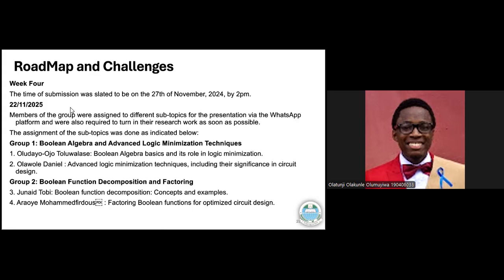If I want to compare it to K-map and Quine-McCluskey, I'll say in a way it is closer to the way we are taught to do K-map, because you take each of the ones, then you group them with the ones around them. That's the expand. Then you're looking at the redundant. When you just group like that, some of the ones are going to be covered multiple times, like a certain one shows up in two groups. So you're going to now reduce. That's basically how it works. So in a way, it is similar to K-map, just that it obviously isn't exactly K-map.